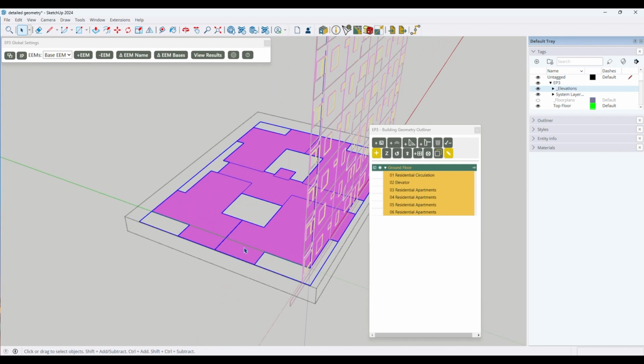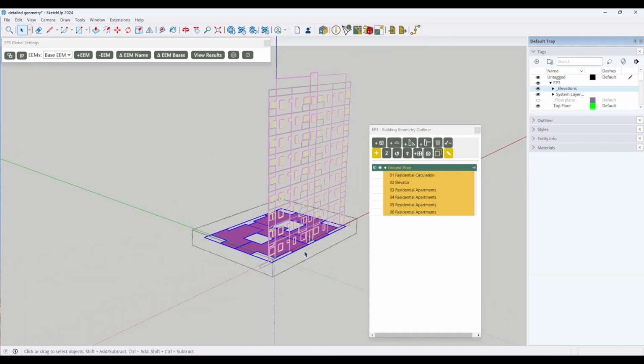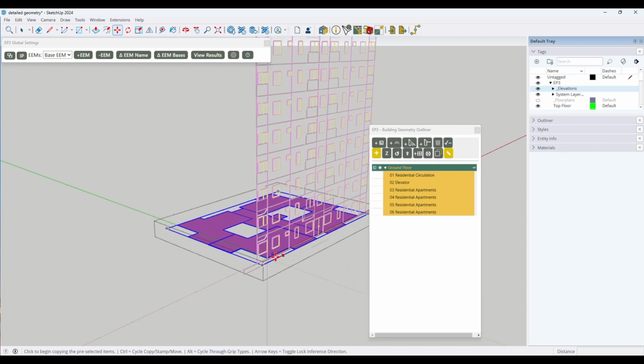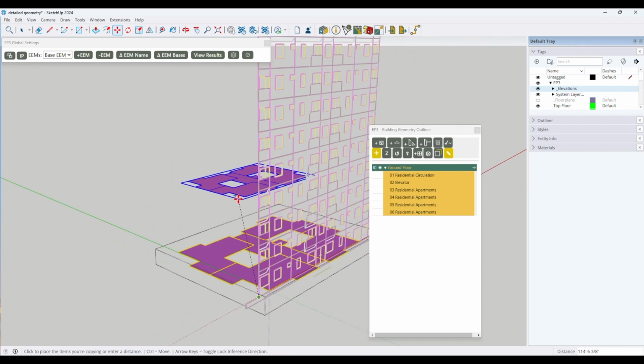Okay, so I have the floor plan selected, so I'm going to move it, copy it, and I'm going to put it at the 5th floor level to represent sort of those middle floors. So to copy in SketchUp, we use the Move tool, which I got to by pressing M, and then you hit Control once, and you'll get a little plus mark next to the Move tool. Now I'm going to click a reference point, which is going to be at the ground level, and I'm going to pick a corner, and then I'm going to click again.